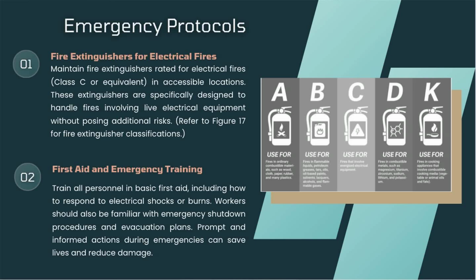Number 2, first aid and emergency training. Train all personnel in basic first aid, including how to respond to electrical shocks or burns. Workers should also be familiar with emergency shutdown procedures and evacuation plans. Prompt and informed actions during emergencies can save lives and reduce damage.